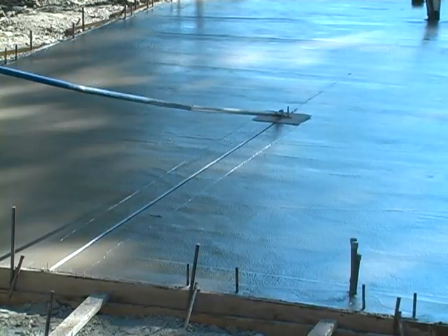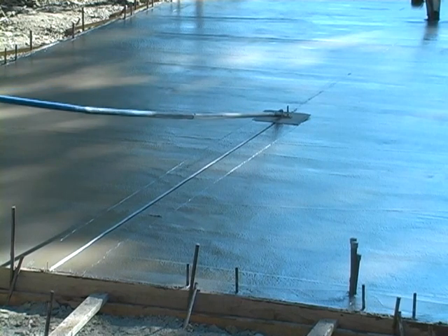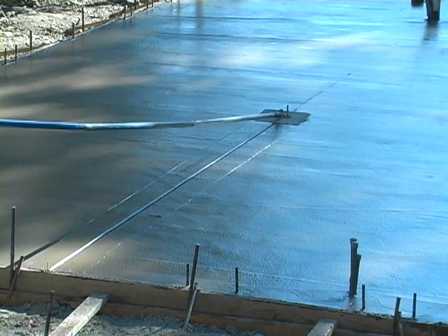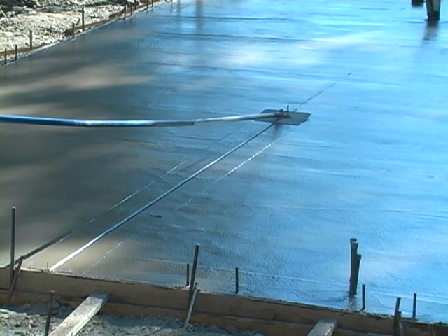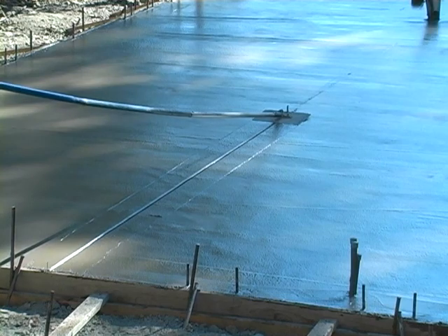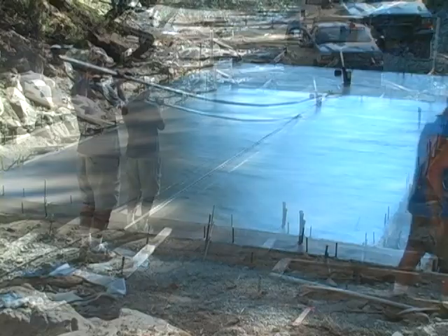Now you see we kind of work it back and forth. We're not just able to push straight through all the way because it's quite hard to push through the concrete. We've let it set up enough already that it's starting to firm up. If we get in there when it's too wet, it'll just squish all over the place and it won't hold the shape of that groover.